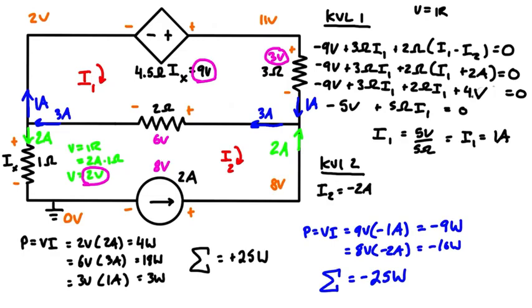So I think that's the last video for dependent power sources. At first they look a little dodgy here because they have a whole bunch of symbols and things, but basically once you figure out the controlling voltage or the controlling current in this case, then you can treat these problems just like any other problem that has multiple power sources, and then we can use methods like KCL, KVL, Ohm's law, and also, as we've seen in this video, mesh analysis, and also nodal analysis.